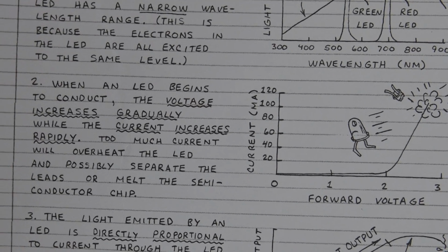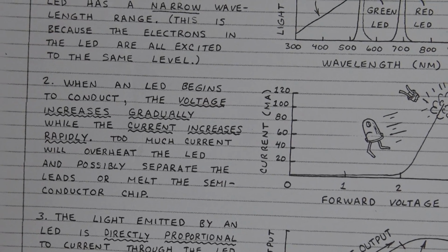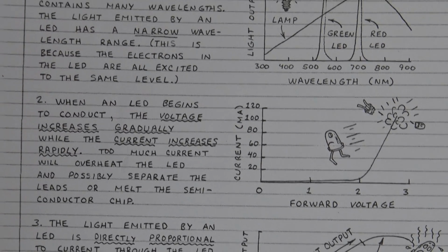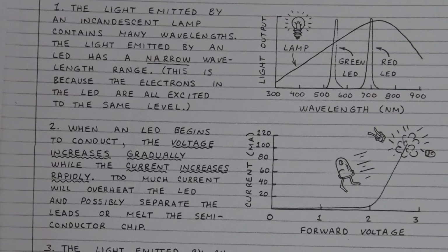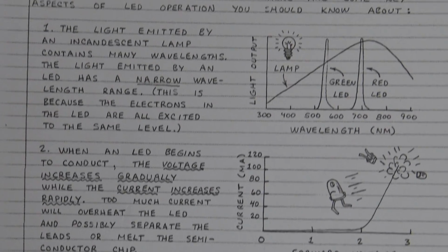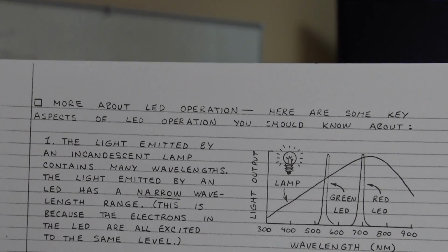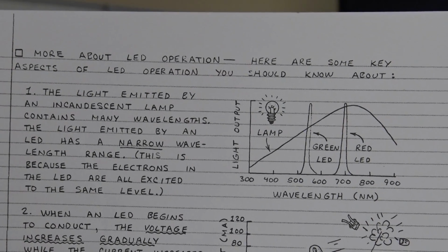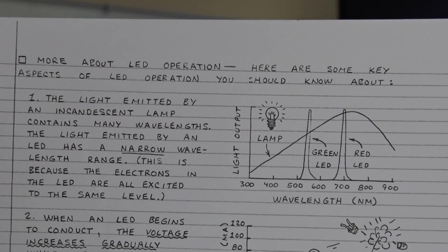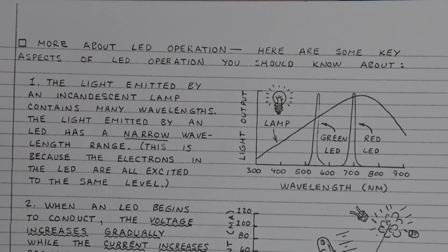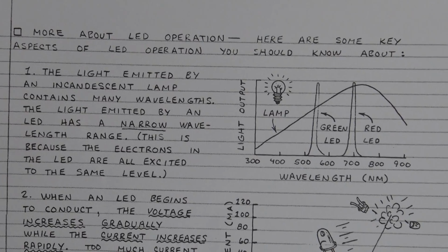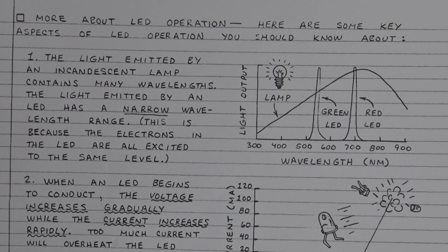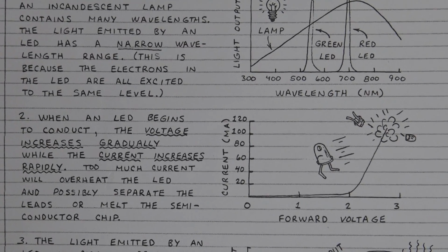Now go to the charts above there, light output. Again, it's got your nanometers, 300 to 900. This is more or less what the eye can see, from 400 to about 700. And then as you see, somewhere in here it talks about the infrared. Here, 400, 900, 940, you get into infrared that you can't see, but these diodes can see. That's why you can have a camera that will show you what this room looks like with the lights on, infrared.